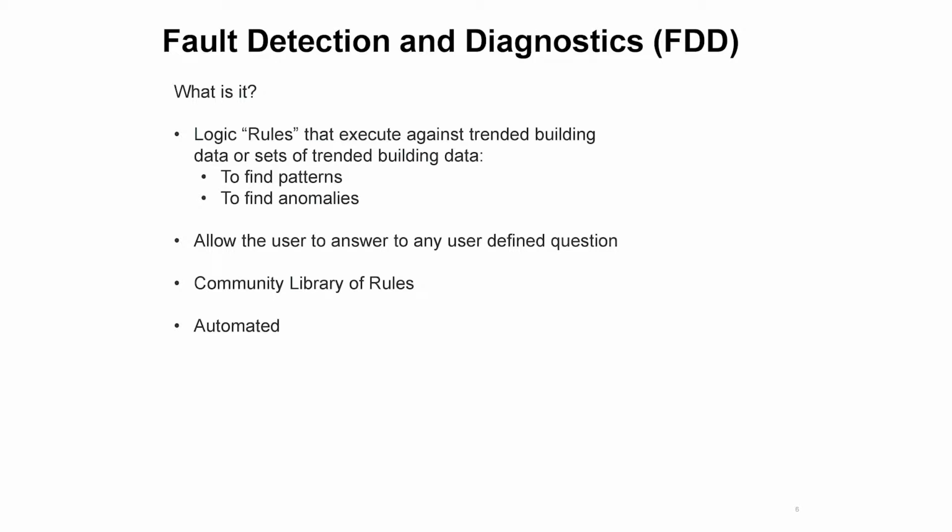All right, so this is just a basic idea of what a rule is. Essentially, it's a number of discrete algorithms that are operating continuously in the background as data from a building automation system is getting fed into these algorithms. An example of one of these algorithms is basically the things you're doing today as part of your functional test procedures during commissioning. We can mimic a lot of that using these algorithms.